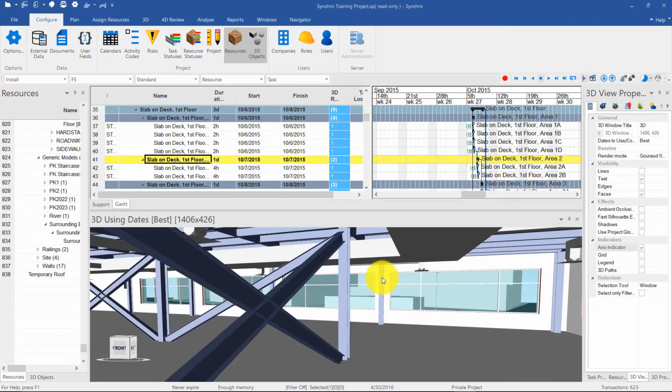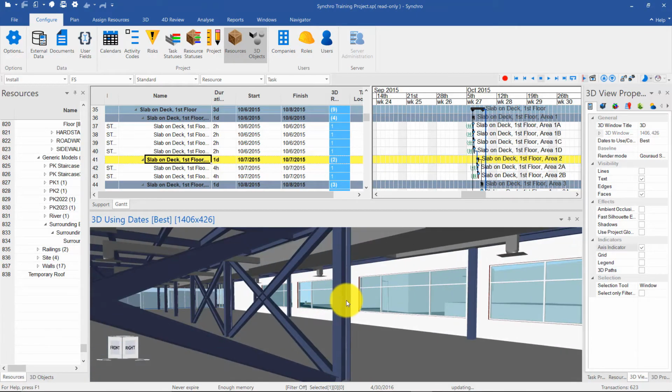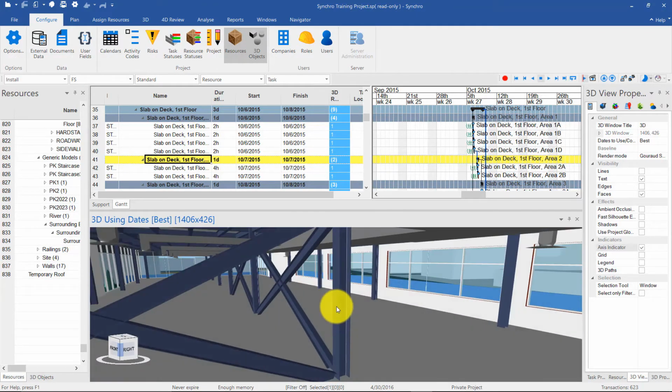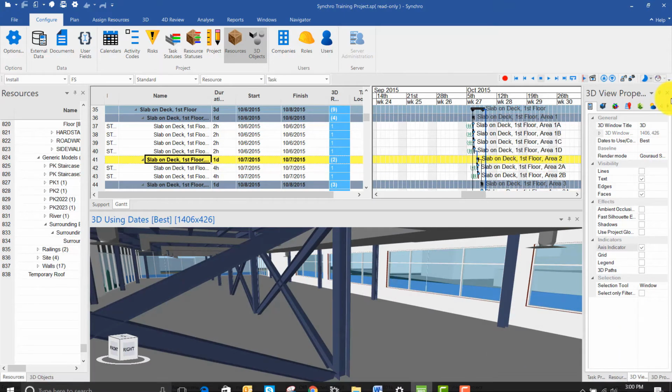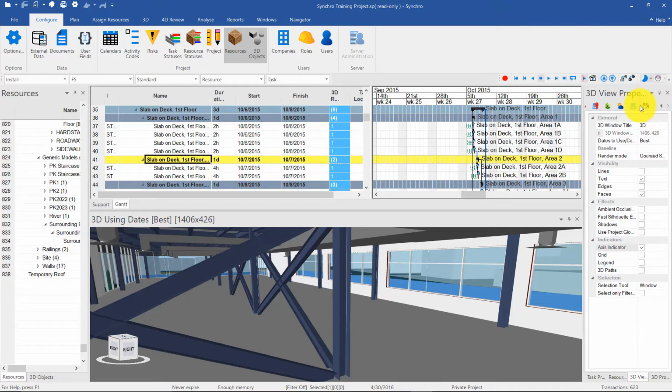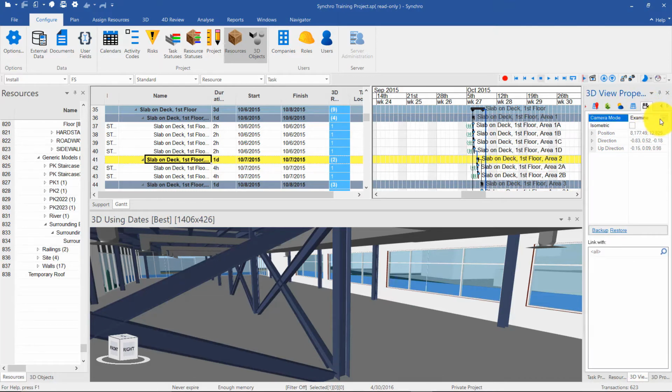Welcome back, and hopefully you've paused the video and practiced navigating the model. We said that we're going to cover a way to more easily navigate interiors of models rather than having to pick elements and rotate about those elements. You can go to the 3D View tab that we've used earlier, the 3D View Properties tab, and then all the way in the end, in the camera options, you can change from Examine, which is the default, and try out different types that may work better.